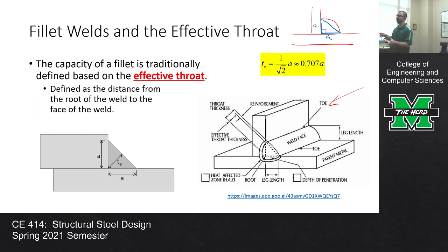So to go back to the question Mr. Thews asked, he said, what about grinding? I said, well, as long as you don't grind into that triangular region, you want to maintain that geometry. If you ground this so far that you were grinding into this area, that would not be good. So that would be my answer about grinding: don't penetrate past that throat thickness.